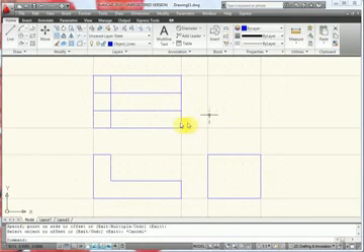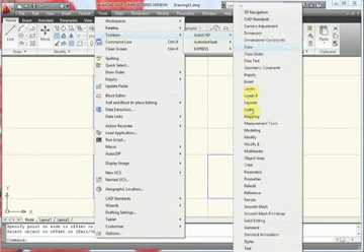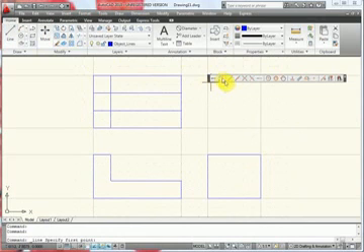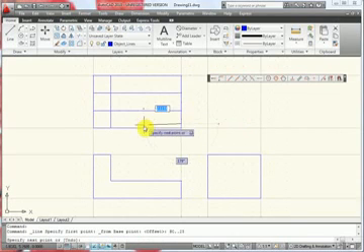Now I'm going to make a few angled pieces back here, and to help me with that, I'm going to use the Object Snap toolbar. So I'm going to Tools, Toolbars, AutoCAD, and Object Snap. So I'm going to use the line command here, and I'm going to use the Snap From tool. So what I want to do is draw an angle that's down in this area right here. So to do that, I'm going to use the Snap From tool. I'm going to click the first point I want to snap from. I'm going to enter on the keyboard at 0, 0.25. Enter. Notice how it snapped me to the top right there.